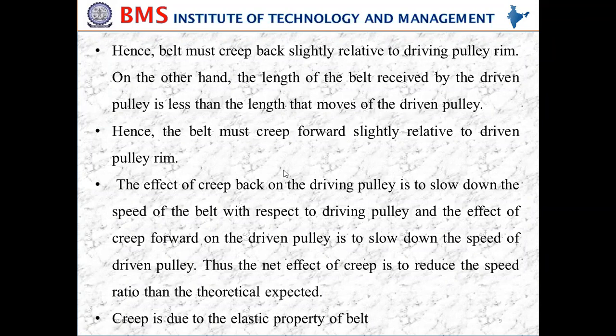The effect of creep back on the driving pulley is to slow down the speed of the belt with respect to the driving pulley, and the effect of creep forward on the driven pulley is to slow down the speed of the driven pulley.